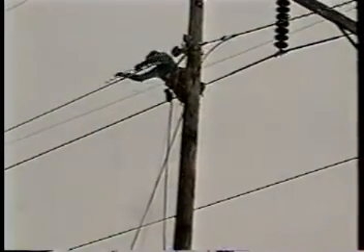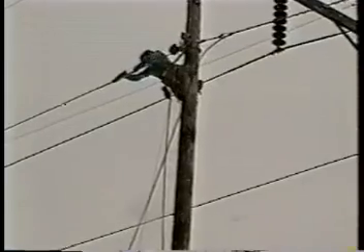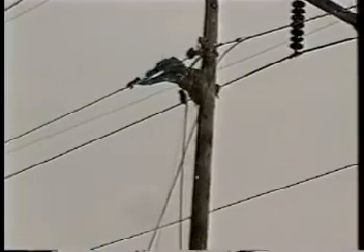Because optical cables are lightweight, adjusting cable sag may be more difficult than with heavier cables. Lightweight cables may also display undesirable effects in windy conditions. Drift, galloping, and vibrations can often cause cable and hardware damage if not remedied. The use of airflow spoilers, vibration dampers, and center span weights can reduce the damaging effects of bad weather.